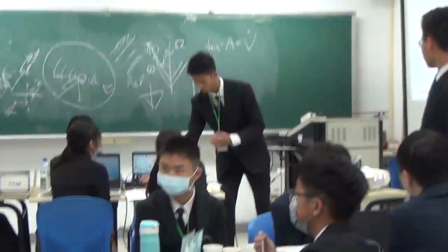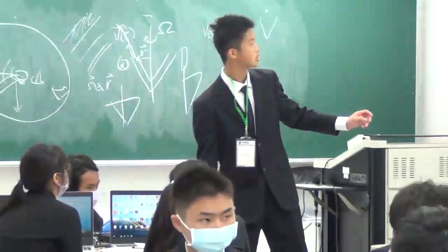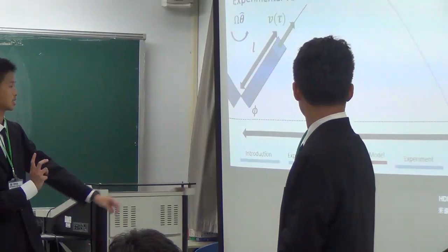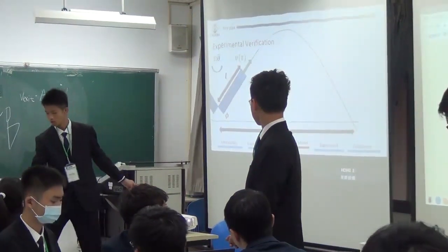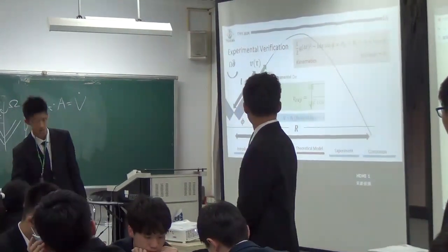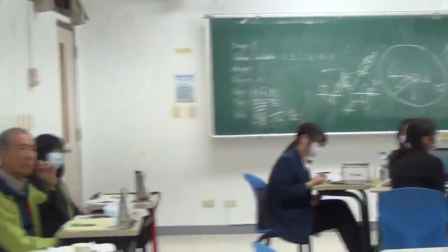Could you describe how you experimentally get the exit velocity? All I can measure is how far the droplets go. So this one, right here. You can see I draw this line, which means the droplets will go in parallel. If we don't consider air resistance, we can measure this range here, the R. We measure it with rulers, and we can use basic dynamics. Basically, half g t squared minus v sine theta, and we use that to determine the exit velocity. So it's just dynamics.